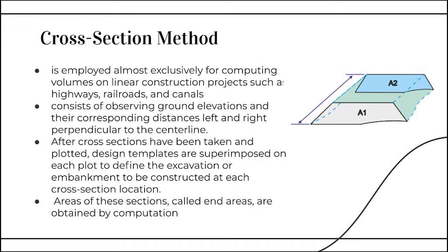After cross-sections have been taken and plotted, design templates are superimposed on each plot to define the excavation or embankment to be constructed at each cross-section location. Areas of these sections, called end areas, are obtained by computation.